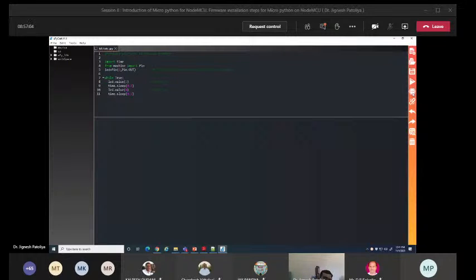And what is the magic? Your program is gone. It means previously we ran this code, blink.py, that is installed in flash memory, and once we disconnect and again reconnect, then my code is gone. So a very important thing behind this MicroPython. Again, suppose I click on this run button; before that I have to open this serial port and again click on this download and run button, and it will come back.